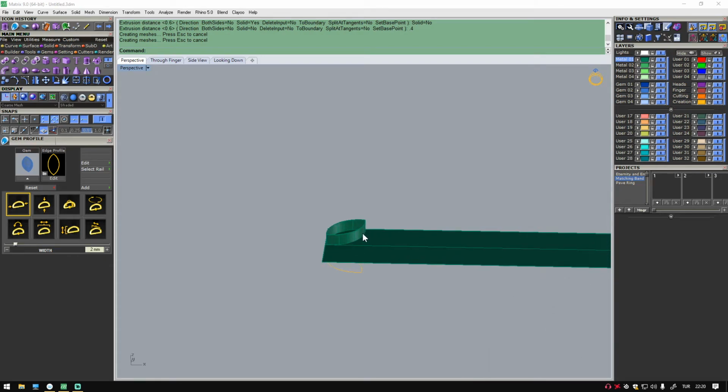Now I want to make a dome top, like a ball, you know. Instead of having something straight, I want it to be curved. So I will go to curve, second page, and I'll duplicate the edges. It's this command here, duplicate edge. Click it once, and if you check up in the command line, it says select edges to duplicate. So it's first and second, and right click.